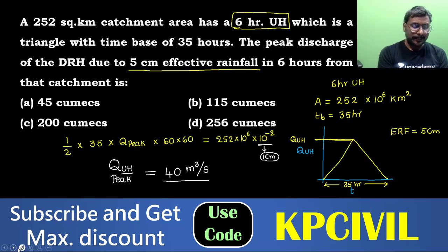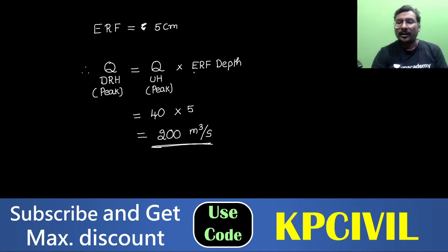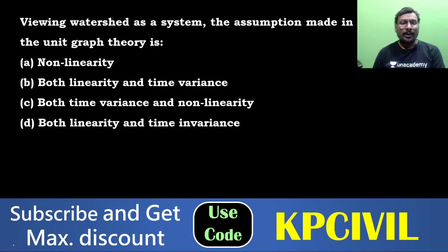What is the answer? Tell me what is the option? Option C, 200 meter cube per second. Clear? First we are deriving peak discharge of unit hydrograph, then multiplied with effective rainfall. Multiplied with effective rainfall, that gives peak discharge of direct runoff.